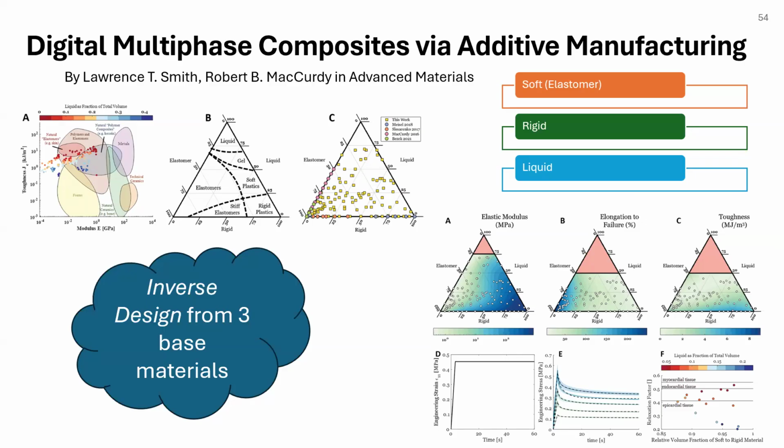And there's a whole other subset of research that predates it. Rob did a lot of this research initially on the liquid printing itself, and on sets of rules that you have to apply for that. For example, if I wanted to print a simple sphere and incorporate 5% liquid, there are already design rules we have to follow to make sure that's even printable. For example, we don't want any liquid on the surface of the object because it's just going to leak out. So there are rules for how much liquid we can place where, which is another branch of future work we're interested in: how can we inform geometric rules for things like that.